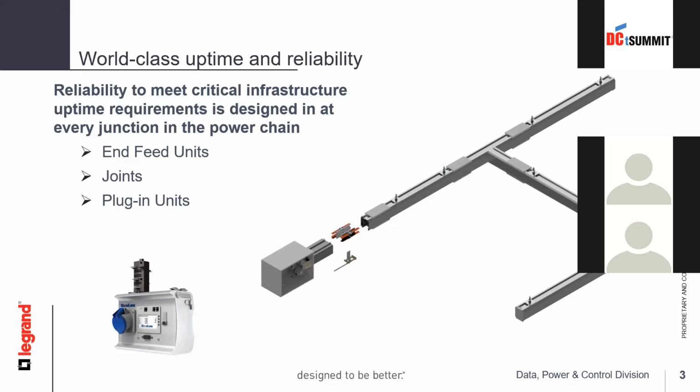So there are options to enhance the reliability. Let's look at some of those options and how Starline can help in achieving those. There are three places where failures can occur within a busway system in the above architecture. The first one is the entry unit. This is where the cables from the low voltage or UPS panel come and get connected. The second is the point where two busways get connected using a joint kit. The third, the plug-in units, also known as tap-off points. We look at these three areas to see how we can improve reliability.